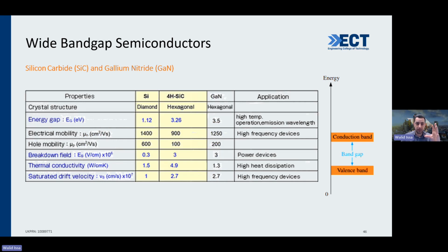Okay, the thermal energy can be released to the ambient atmosphere very easily. So if that number is higher, 4.9, that means it doesn't trap it inside. It releases it to the outside easily. So that's the thermal conductivity point, and that means my transistor will not heat up very quickly, and it can handle the higher current as well.